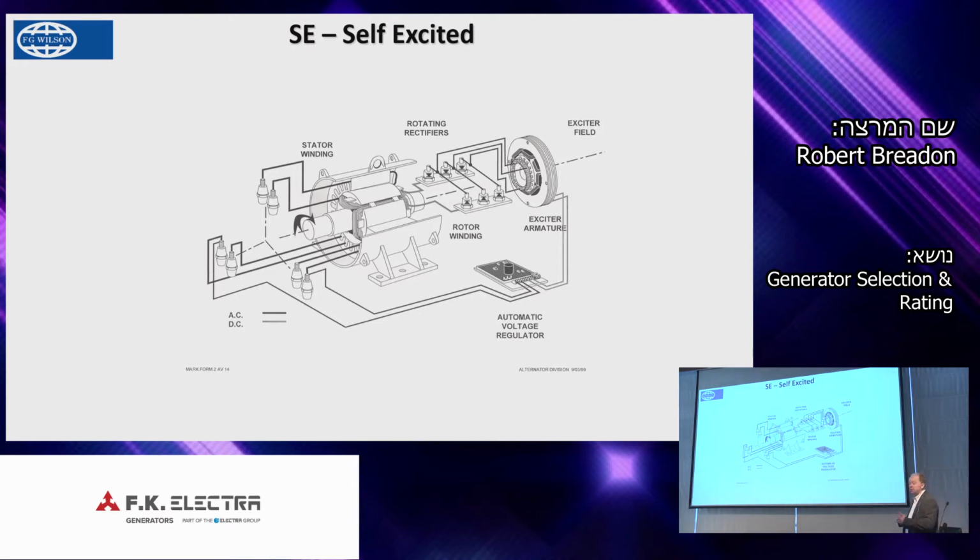The simple one, the standard one, is self-excited. So the power for the excitation is taken off the terminals, same as the monitoring or reference voltage. So that's 90% of the product that we supply would have this type of excitation, and it's also known as shunt excitation.